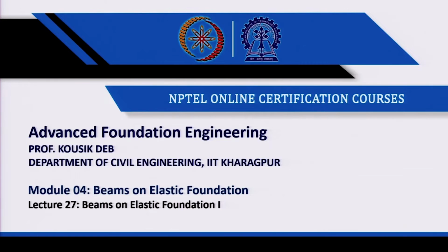So, this class I will start one new topic, that is beams on elastic foundation. In my previous lectures I have discussed the bearing capacity and settlement of shallow foundation, and during that discussion we have seen that we have not taken the foundation soil interaction, because we have taken the foundation as a separate part and the soil as a separate part in most of the cases. So, we have not considered the foundation soil interaction.